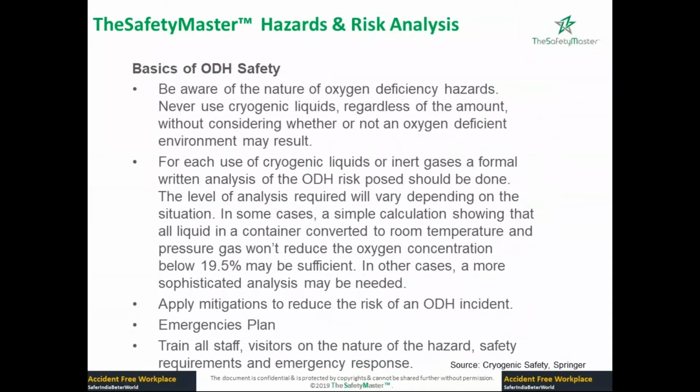Okay, now the basics of oxygen deficiency hazard: you should be aware of it, but never use cryogenic liquid, regardless of the amount, without considering whether or not oxygen deficiency may result. There will be oxygen deficiency whenever you're using a cryogenic liquid, especially the inert ones: liquid nitrogen, liquid argon, liquid hydrogen or liquid helium. You will always have this oxygen deficiency hazard.